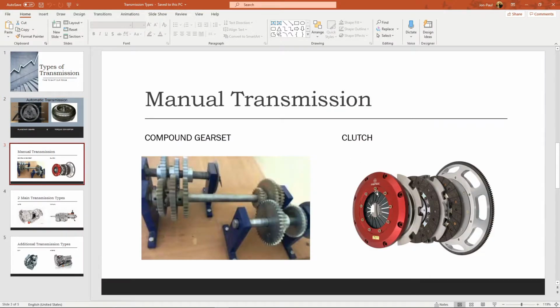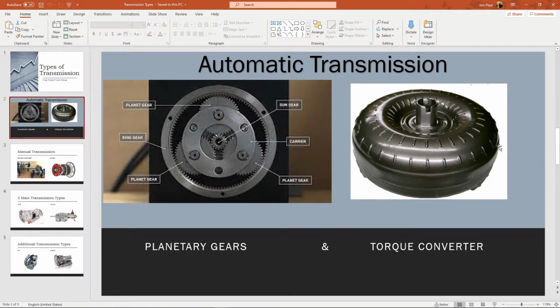Last week when I asked you what was the purpose of the clutch, your answer should be to allow the engine and transmission to disengage. So next month when I ask you what is the purpose of this torque converter, the answer needs to be to allow the engine and transmission to disengage. The torque converter is cool because you won't believe it, but it does do some torque multiplication. However, because it's a fluid coupling, there is some power loss, which creates a lot of heat. So, one way, half a dozen one way, six another, which one is best?